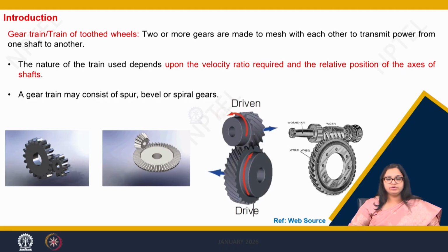However, when the friction is lost, there will be slippage between the friction wheels. So, for that there should be teeth or protrusions around these friction wheels, which we call toothed wheels, which you can see in the form of gears, helping us in power transmission.